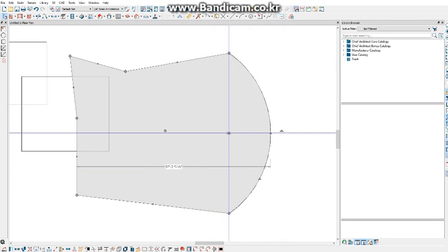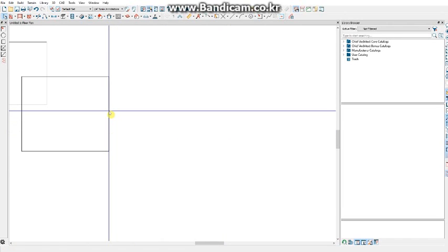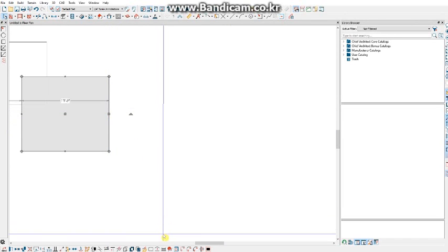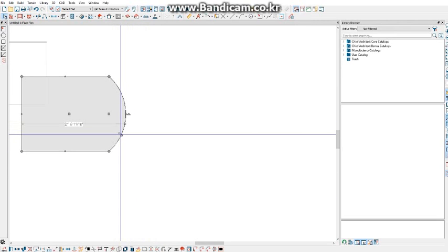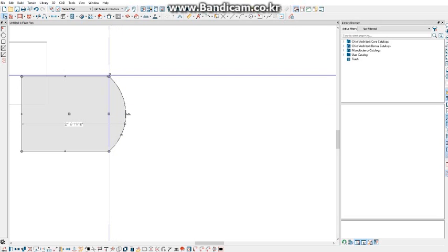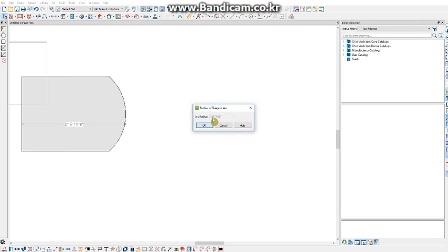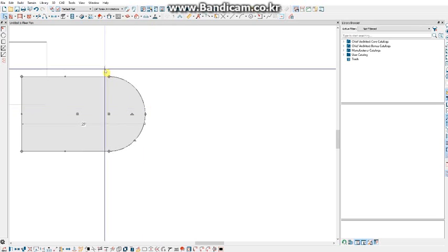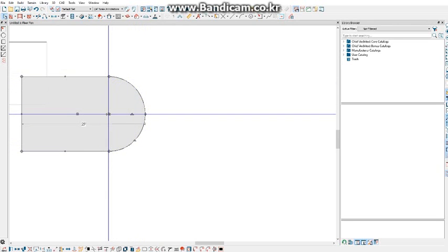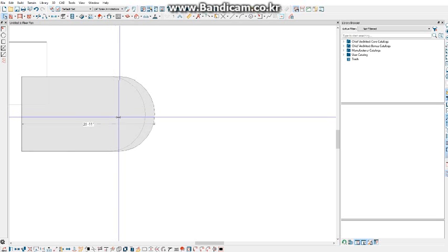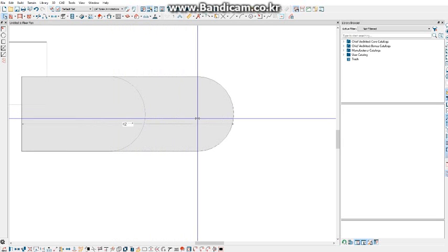I'll go ahead and delete this polyline and use this polyline. Select this edge and use my Change Line to Arc tool. We can change the radius of this arc to be tangent to its connecting lines by using this tool, Make Arc Tangent. Chief will automatically calculate the radius needed to create that perfectly rounded end. If I select this Move edit handle between the 2 endpoints and drag it out, it'll simply move the entire arc and extend the lines it's connected to.